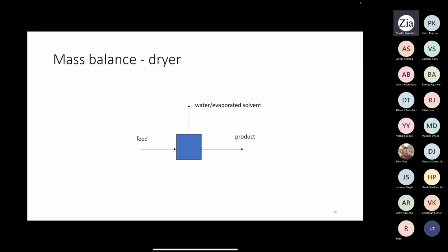Similarly, a dryer is also one kind of unit operation or system which will help you to remove moisture or separate liquid from solid. In bioprocesses, you will have a little bit of difference from chemical processes, because in bioprocess mostly we deal with heat sensitive material. In chemical processes, wherever you use a dryer, you could easily use temperature as a driving force to increase evaporation.